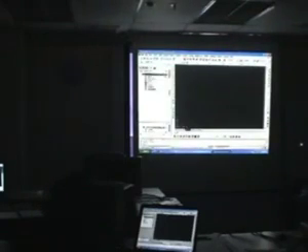Because of this, they look at Land Desktop, okay, these are the functions we want to retain inside Civil 3D. So you find the functions are the same. Functions are similar, but it's just that the way you use them is quite different. One of the major differences between Land Desktop and Civil 3D is the platform that they use. Land Desktop uses projects. Like just now I mentioned, you can only open one drawing at one time. If you lose a drawing, it doesn't matter. You can always call the information out again because it's all based on the database.